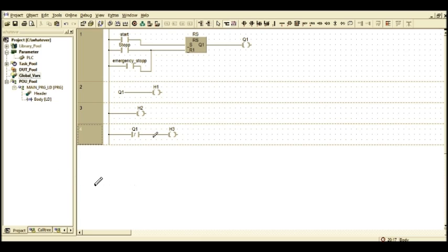And the H3 is used as a normally closed button here, as it will have to be when it stops or starts, if you could call it that. When Q1 starts, it will open up the button, and H3 will not be given a current anymore, and there will be no light from it.